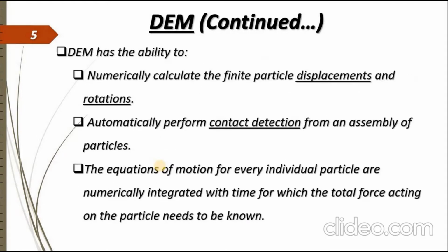It has the ability to numerically calculate the finite particle displacements and rotations and automatically perform contact detection from an assembly of particles. The equations of motion for every individual particle are numerically integrated with time, for which the total force acting on the particle needs to be known.